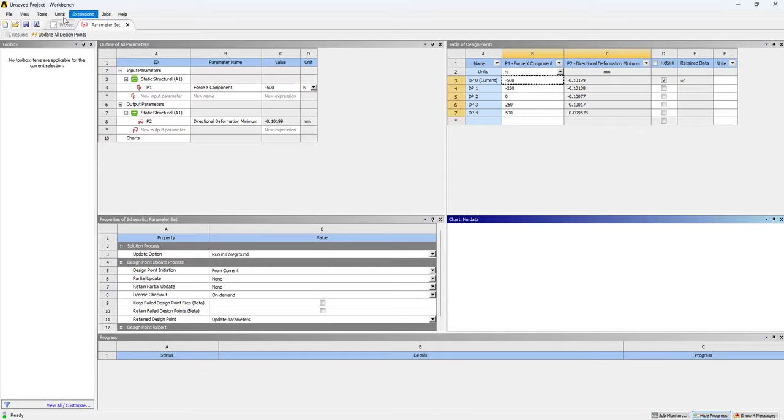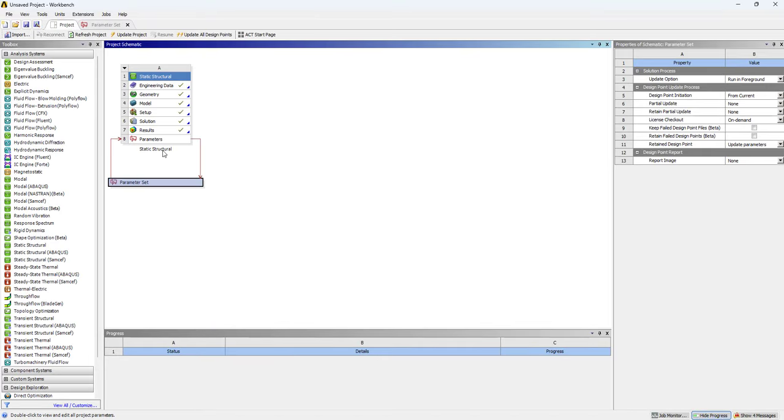Let's move on to buckling analysis and see what the results are. If we want to analyze buckling, you will see another module on the left side, Eigenvalue Buckling. You can click and drag and drop this eigenvalue buckling onto the solution of the previous result.